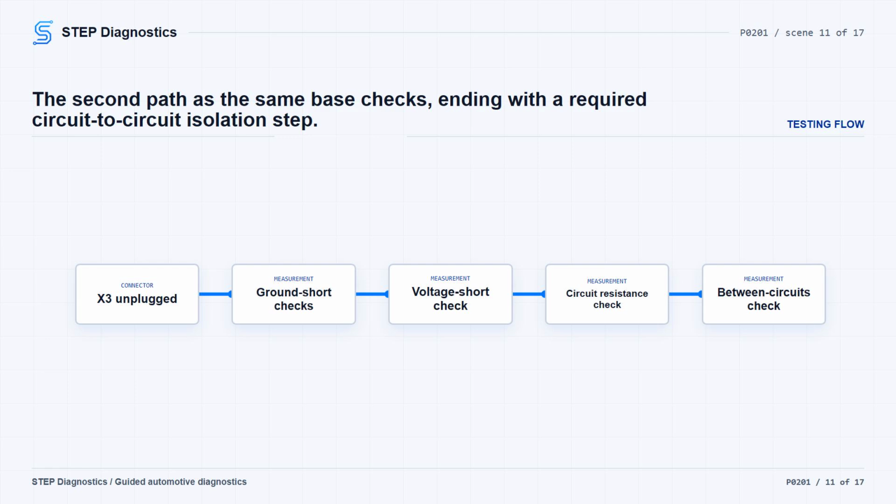A reading of 1 V or greater is handled by disconnecting the injector and separating whether the short to voltage is on terminal 72 or the corresponding terminal 52 circuit. Once the voltage check passes, turn the ignition and vehicle off, disconnect the injector, and check terminal 52 to injector terminal 1 and terminal 72 to injector terminal 2 for less than 2 ohms. Repair any open or high resistance if you find 2 ohms or greater.